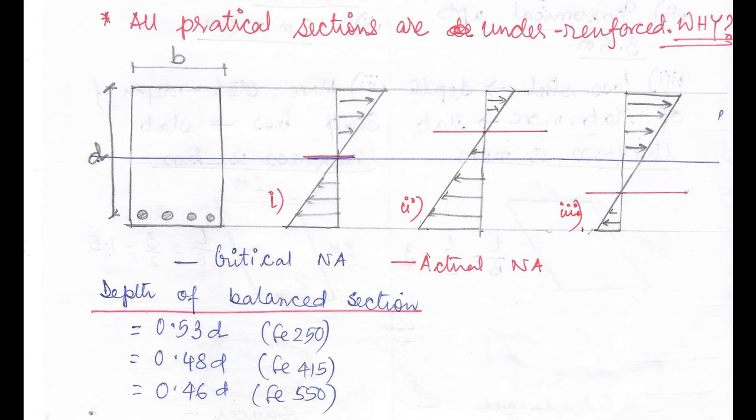Whereas concrete, being a brittle material, doesn't give any signal before failing. It just breaks or fails. So all the practical sections are designed as under reinforced sections.